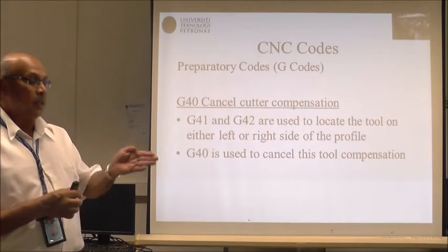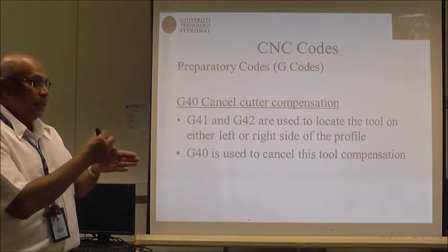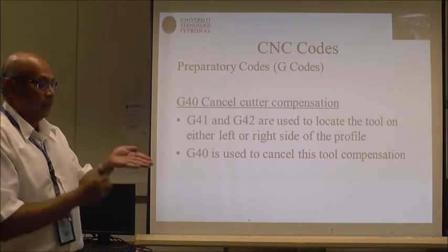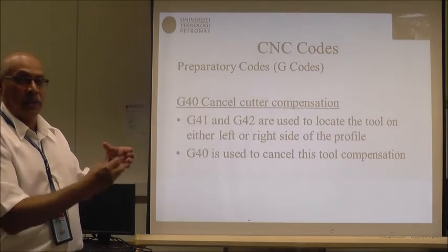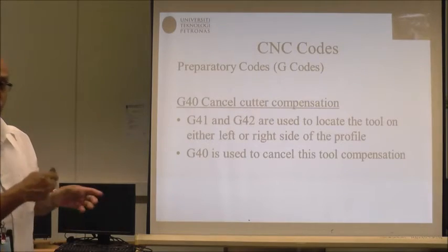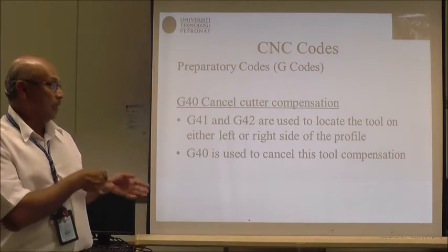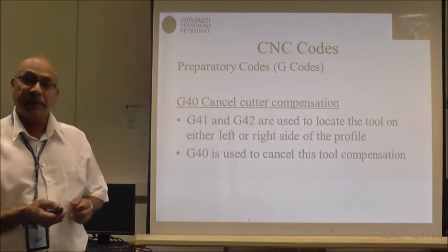If you are making a rectangular island, then you want to be outside cutting so that you get the island. If you want a hole, then you want to be inside so that you cut the hole. We will do a worked example so that you are clear about this. Alright, next slide.